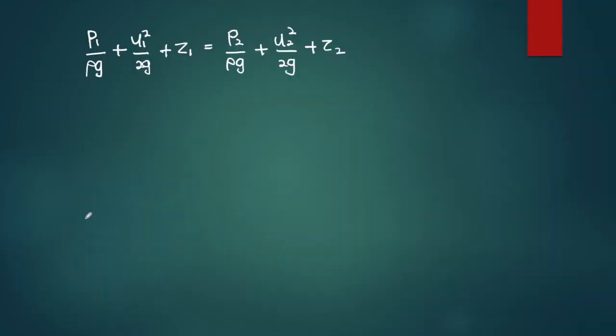So in this question, we will cancel out the pressure energy terms at 1 and 2, since P1 equals P2 equals P atm. Bernoulli's equation only involves gauge pressure, and for the pressure at the end, we will zero it.